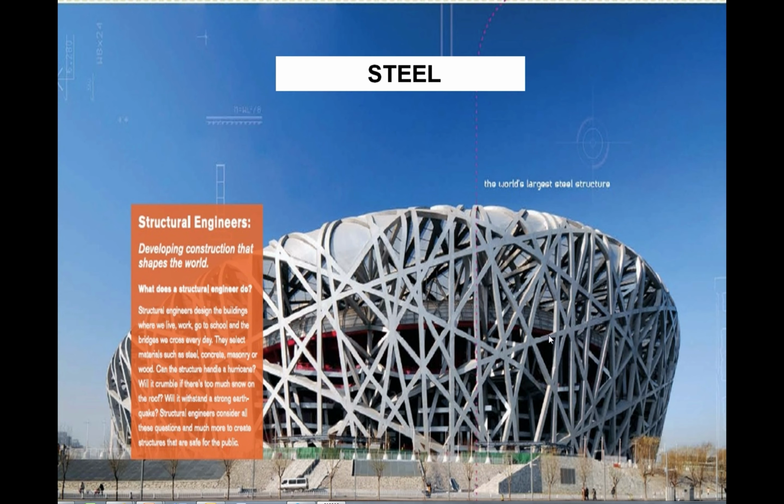And the lengths of all the structural steel are pretty much laid out and detailed in your shop drawings and come to you fabricated. And it's also easier to get into the production line at the mills. You don't have to wait so long for it if it's a typical member. Whereas if it's something like this, a shop needs to basically be dedicated only to your project to be able to knock out the production of these kinds of beams.